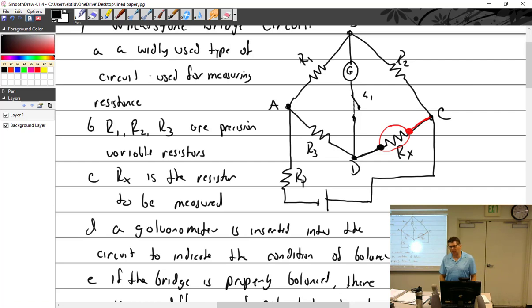Every time you short out your leads and zero it out, you're balancing out the bridge circuit. With your leads shorted out right here, you balance it so that one side is equal to the other. Then when you take it off and put it on a resistor, you're out of balance. So current tends to flow through the out of balance and back around.